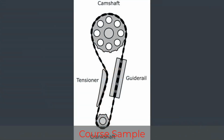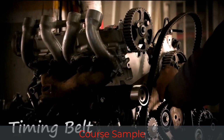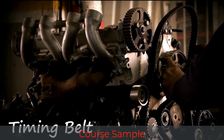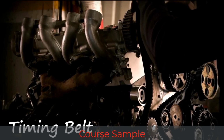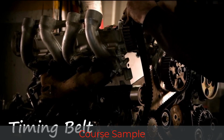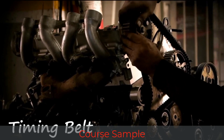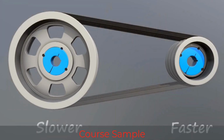What's interesting though is that the camshaft is driven from the crankshaft via gears or a chain or a belt, and although it's the camshaft that controls when the valves open and close and when fuel is injected, etc., because it's coupled to the crankshaft, ultimately it operates with the crankshaft. As the crankshaft rotates, the camshaft rotates also. The difference is that the camshaft rotates slower. The camshaft rotates at half the speed of the crankshaft.